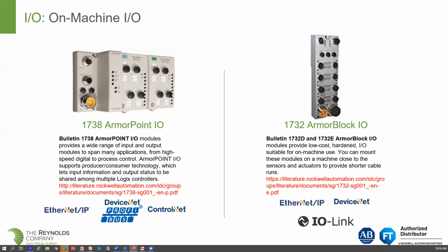We don't see it in our market a lot, but quite often where you'll see this is where you might have robots, welding machines, or any assembly line. Food and bev also is where they'll put it, where they don't want to put junction blocks. They want to put the IO block directly next to the equipment. One thing you'll notice, it uses M8 and M12 connectors for the IO. So it makes a very clean install when you're just trying to connect sensors directly to your input block.